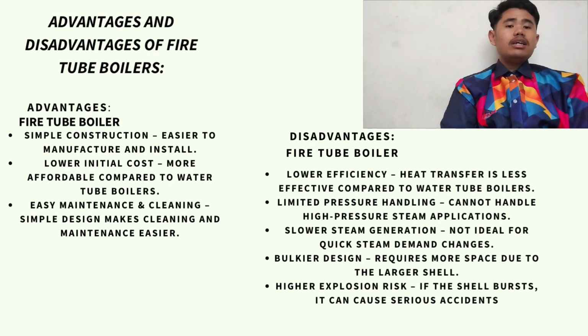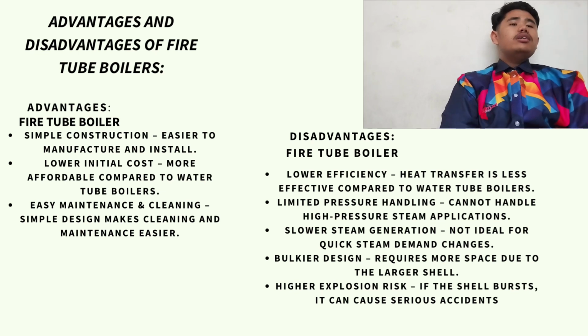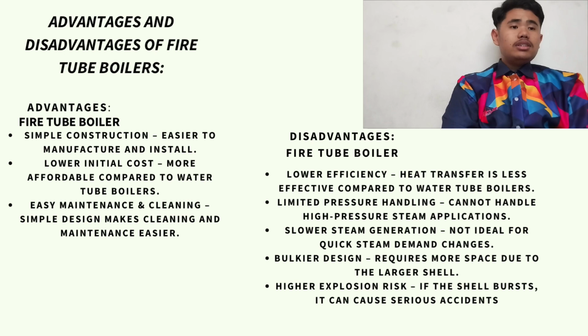And the disadvantage for fire tube boilers is lower efficiency. Heat transfer is less effective compared to water tube boilers. Limited pressure handling, cannot handle high pressure steam application. Then, slower steam generation, not ideal for quick steam demand change.